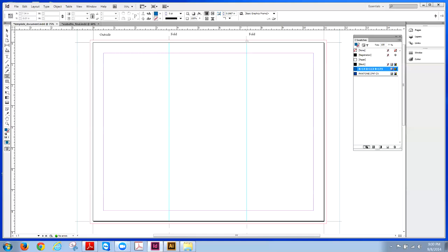Now, I'm going to create a cover. Watch what I do here. I'm up outside on my bleed area, sitting right over top of the fold. You can tell the fold, that blue line that leads up to that line right there is where it's going to fold. So I'm going to hit the fold, click, and drag all the way down to the bottom and all the way over until it's bleeding. Now check this out.